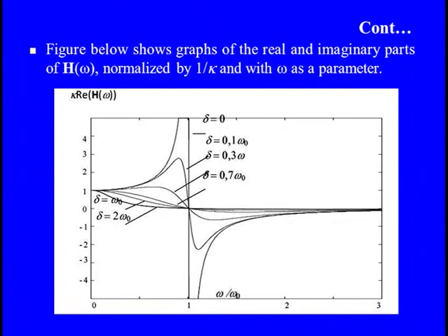So, here when we go from 0.1 to 0.3 to 0.7, or even exactly at omega 0, you can see that when zeta is 1, straightaway you have a critically damped system, and the entire vibration is damped out. Or even when we apply a higher value of damping, that is the over damping case, certainly it will delay the steady state response. So, we need to optimize the thing in that way.